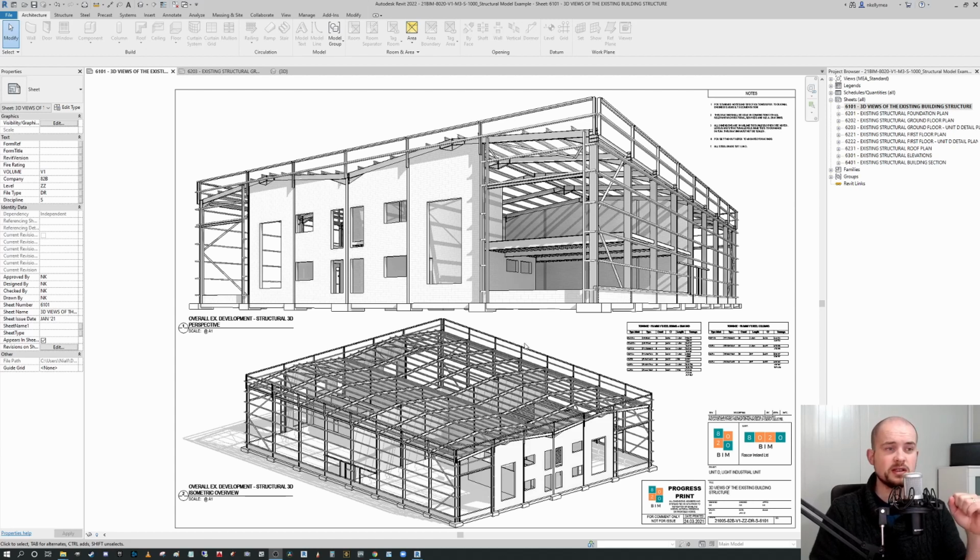So feature number 5 that has been rolled out in Revit 2022 that I feel not enough people have acknowledged is the fact that the modified toolset now actually remembers your previous settings. Not only does it remember your previous settings, it remembers them between sessions. So if you close your Revit dialog and reopen it, it will remember that as well. And I'm going to maybe go through a couple of examples of what tools retain what information between sessions.